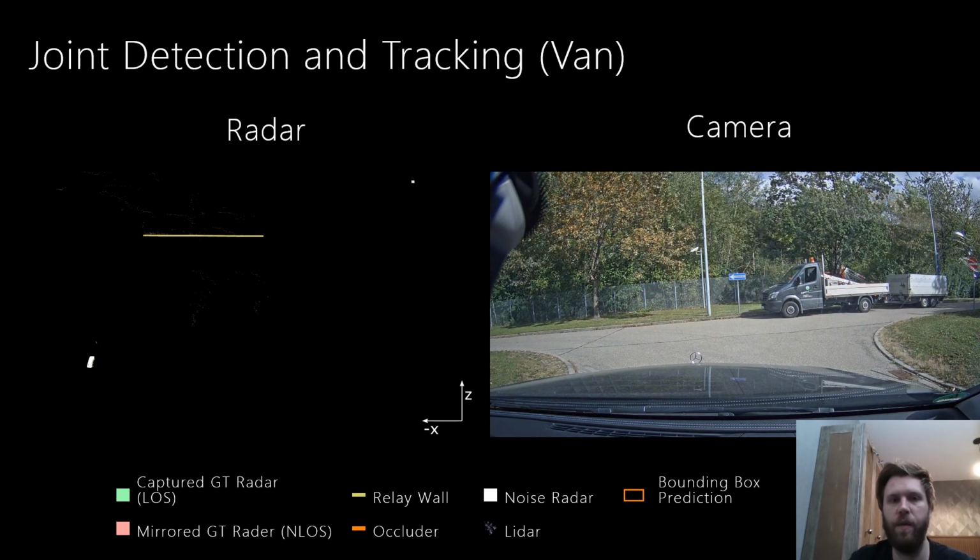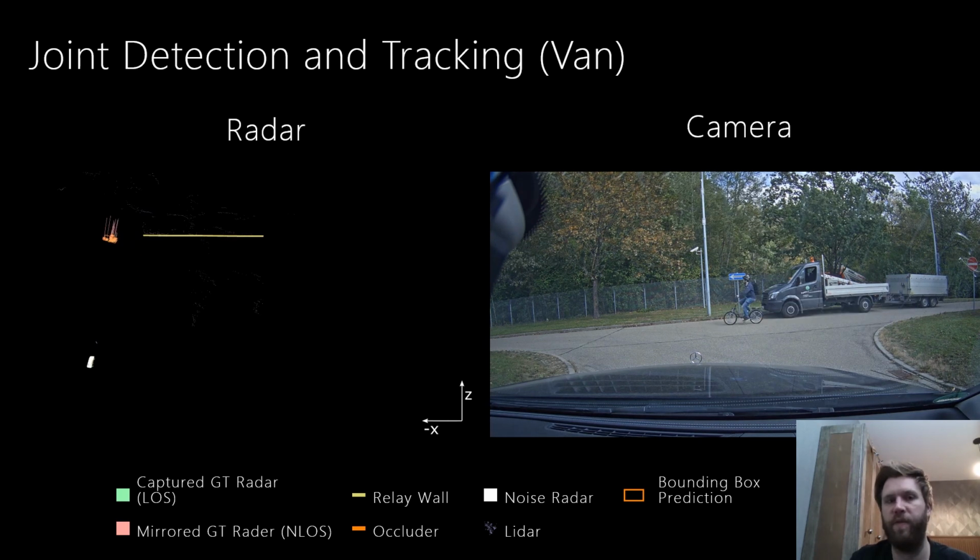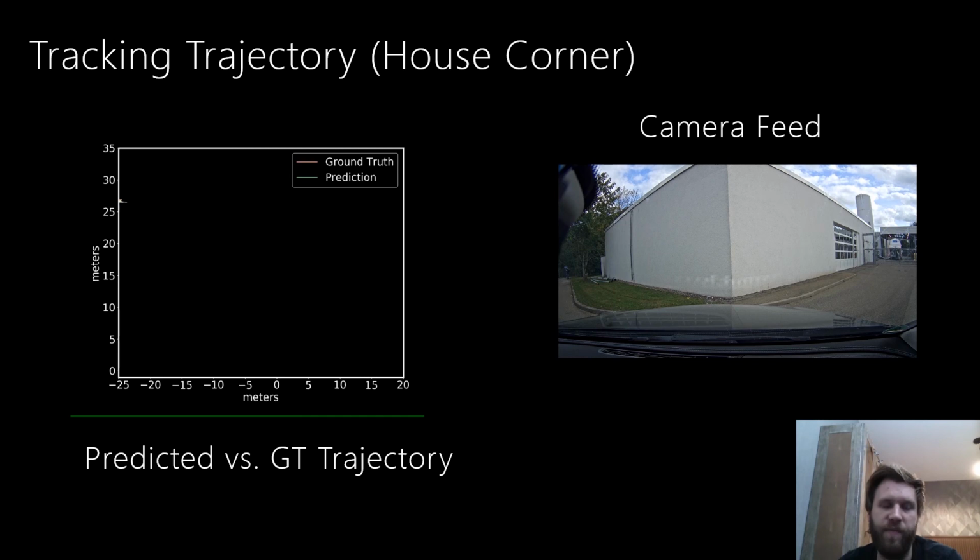And you can see here that this new breed of computational imagers allows you to see much further where conventional line of sight sensors cannot provide any signal anymore. The signal of these indirect reflections is considered to be lost. Here are tracking results for a scene that is visible to the camera. We rotated the camera slightly to make it visible. And the proposed approach achieves on average under 20 centimeters localization accuracy for non-line of sight detections particularly.